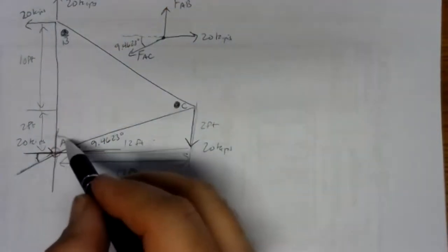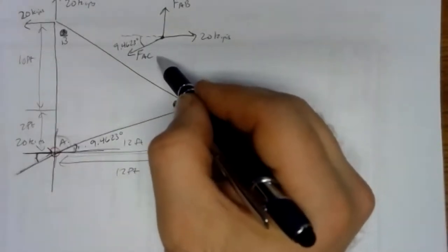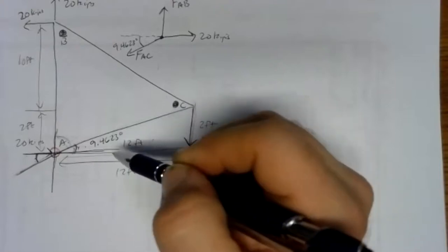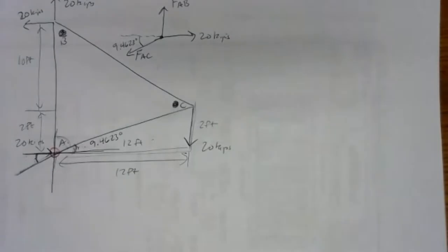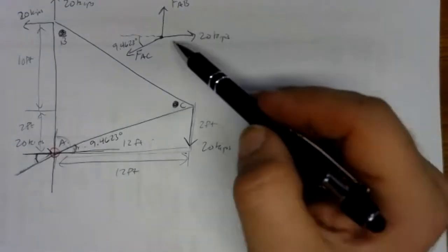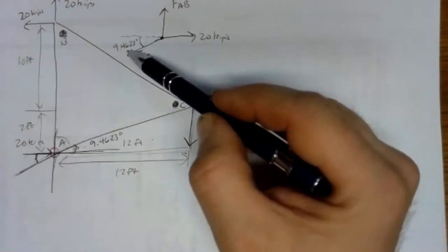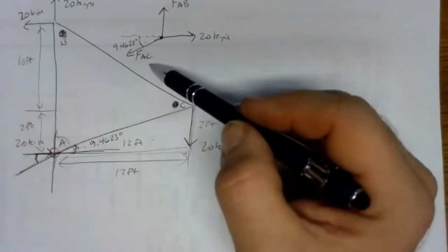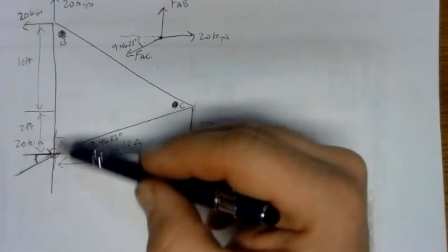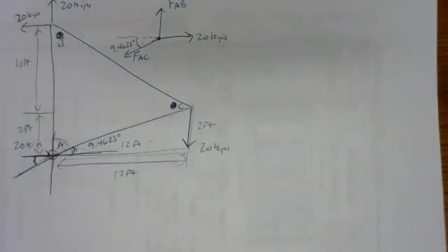Now you could have certainly found the other angle here. You could have found the angle to vertical and used that. That'd be the complement to this, about 81 degrees or so, 80 and a half degrees. But either way works, as long as you've got that in the right place. I can't tell you how many times I've seen people draw this angle, but then label it with the complement. Label it with the wrong one, and that messes everything up. So be absolutely sure you've got the right angle. Sketch out anything you need to make sure that you've got the right angle in there.